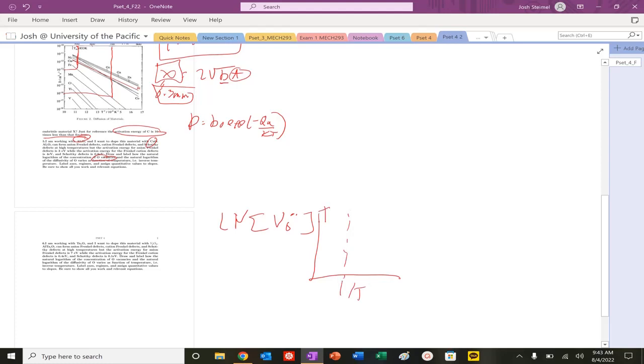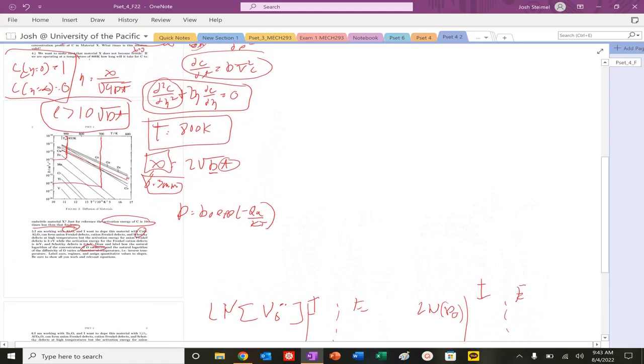We're going to have our intrinsic at high temperatures, our extrinsic at low temperatures, and then natural log of the diffusivity of oxygen versus 1 over T. And we're looking for those slopes as we usually do, intrinsic, extrinsic. So let's start up here. I know that my dominant defect is Schottky for Al2O3.